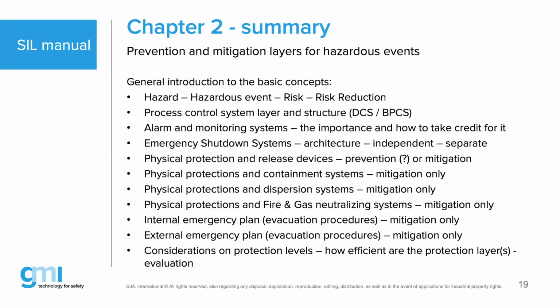When you hear functional safety, you hear a SIL class. A SIL class is nothing more than a performance band providing you with a specific risk reduction. Process control layers: in the older days, we used to call this distributed control, that's DCS systems. Today, in modern society, engineers call it the BPCS, meaning the same thing. It's a basic process control system. You're trying to measure your process values, you try to control them, and you try to regulate your control valves so that you reach a certain level, flow, pressure, etc., etc.